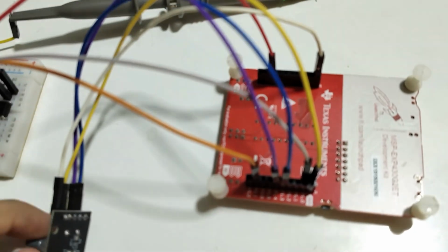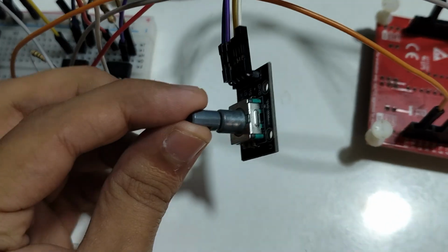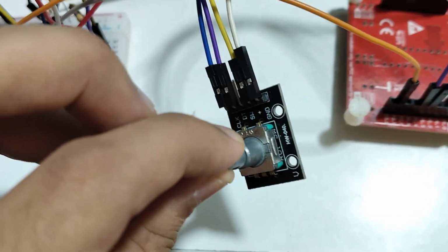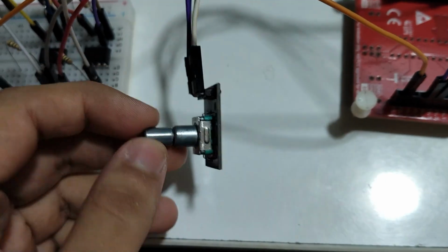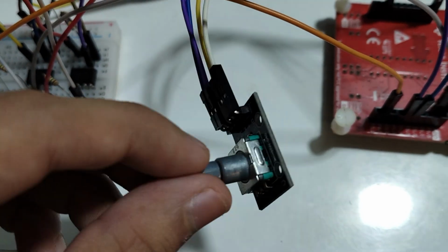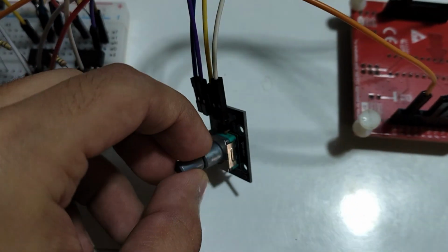And another thing I'm going to be using today, of course, this is still open loop, so we do need something to vary the duty. And we're going to be using the rotary encoder. I have made a video on this too. It's just like a pot, you could say, but it has endless rotation. Pots do have limits, and they manually vary voltage. That's what a potentiometer is.